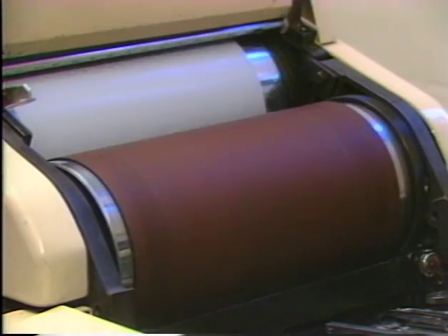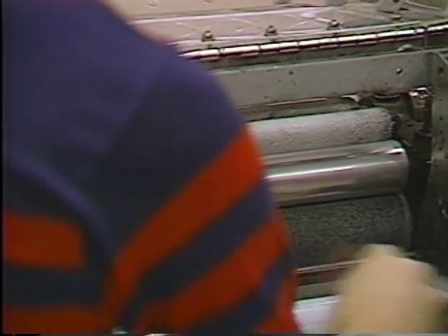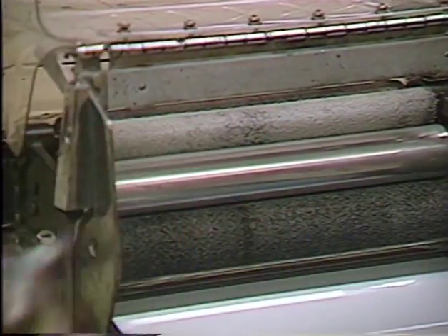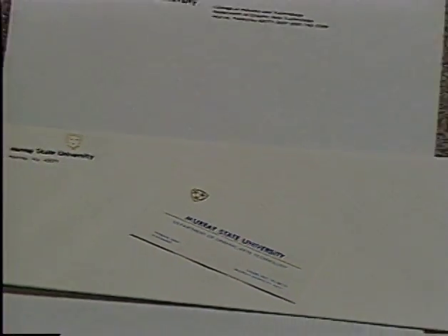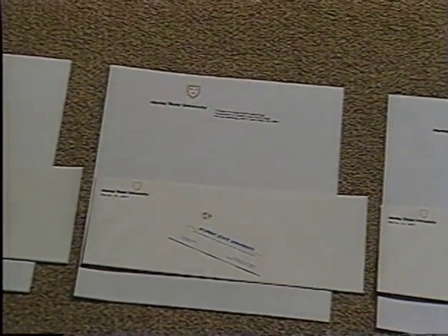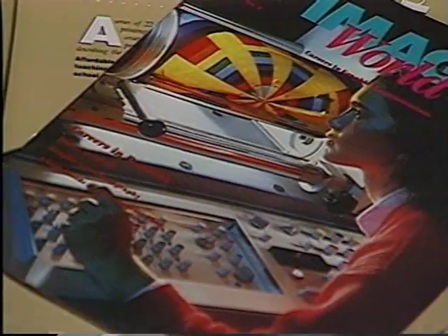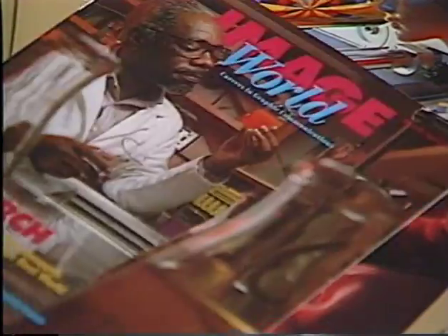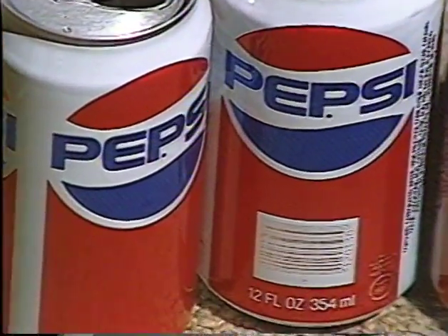In commercial practice, a printing press first moistens and then inks a printing plate. The image is transferred from the plate to a rubber blanket. The rubber blanket transfers the image to the material to be printed upon. Offset is used for general commercial work such as letterhead and business cards, forms, publications printing, packaging, metal decorating, and other applications.